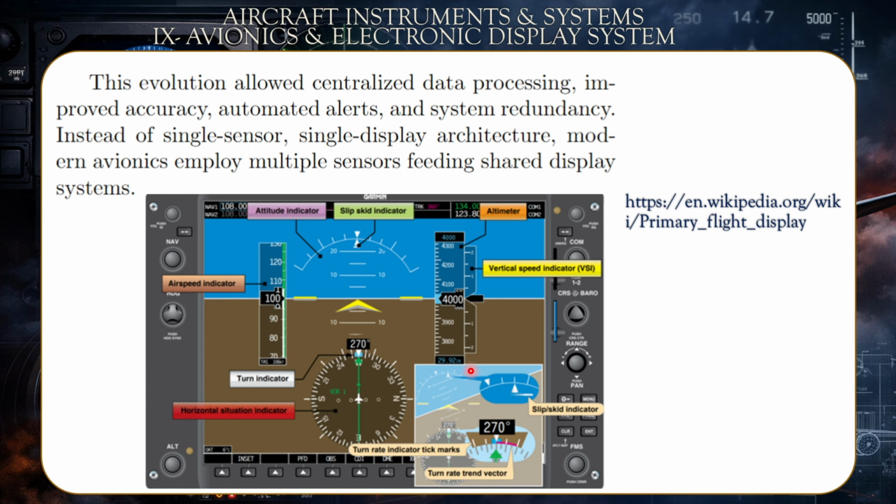Now, note that in order to have redundancy, you would also have some of the instruments in analog format in case the screen fails for some reason, or the computer malfunctions. And to add to that, you would have different types of alerts, such as the stall alert and other types of alarms appearing on this very same screen, like when you have a retard in the engine, which is a maneuver during landing that was installed by Boeing.